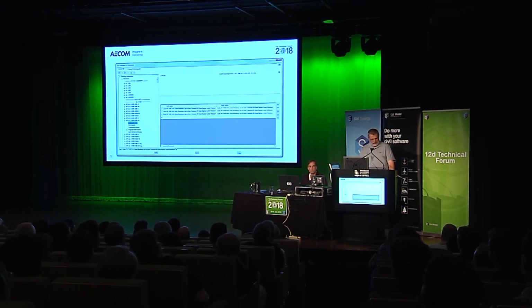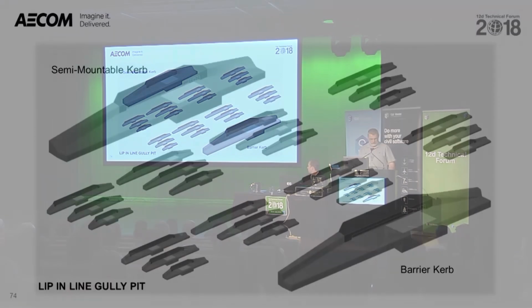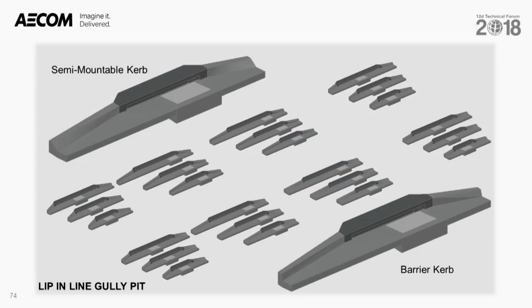Right, we talk about the 3D library of drainage structures, with 24 variations needed for each pit style to take into account lintel size, channel width, inflow configuration, and orientation relative to the curb. Now, these have always been defined for hydraulic reasons, but we're now also needed to take into account the curb type, not for hydraulic reasons, but to include in the curb transitions in the trimesh and ultimately the federated model.